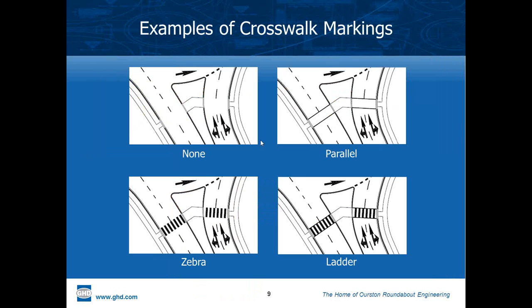The types of crosswalk markings that we see, in the first photo that I showed you of a roundabout, there's this ladder style with transverse lines, as well as the longitudinal lines, or the zebra crossing as it's sometimes referred to, which is this design over here. I think in Canada they use the zebra crossing in rural designs, and they use the standard transverse bars or parallel in urban considerations. I think an agency should choose one or the other and not really mix and match.